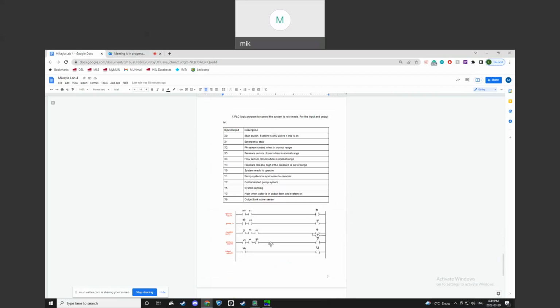And then the PLC ladder logic here. Again, this includes most of the inputs that I just mentioned, as well as some outputs to indicate what's happening in the system. The first rung here would be the general generator start, which I just mentioned. The operator would have to have that input start activated first in order for the system to run at all, and that's really a safety measure. Next, I'll have a pump input. This would be controlling the pump. If there is power coming in from the solar panel and the operator of the system turned it on, we'll be able to get the pump running.